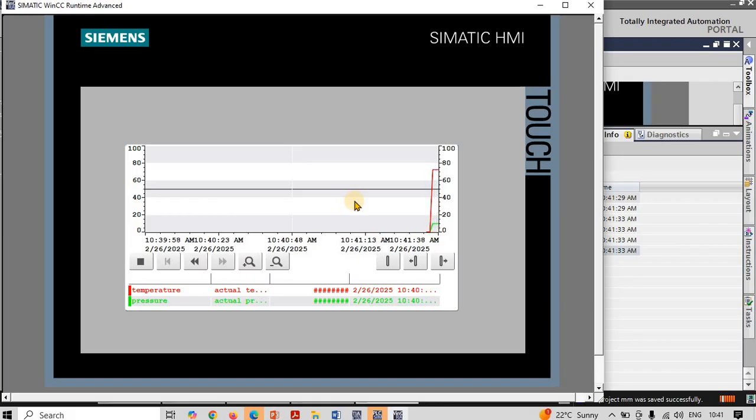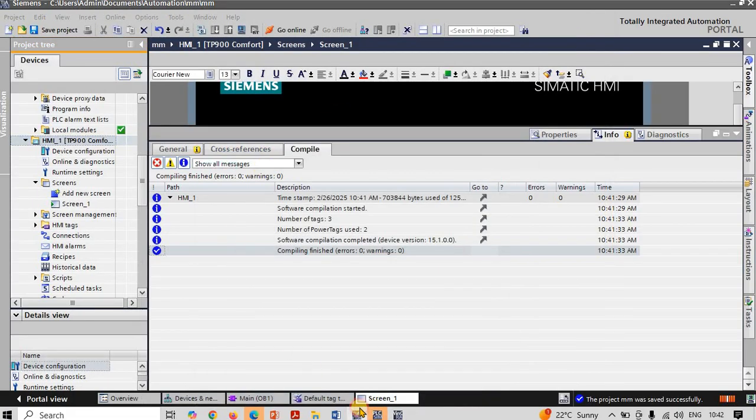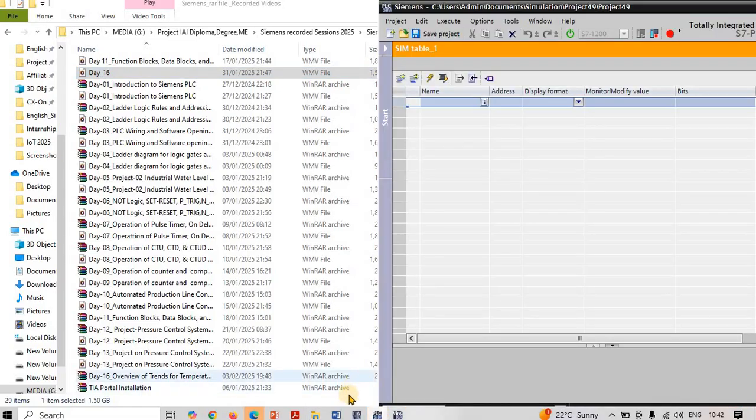Okay, and again no errors, no warnings, and we'll see what the results are, right? Okay, now you can see everything is perfect. So trend value means what they are talking about is 0 to 100. No need to put your pressure range and temperature range, so that we have already put into the PLC programming. So when you enter the tag, you are getting the values directly, right? No problem at all. You can observe the values directly over there. Okay, so these are the trends, right?